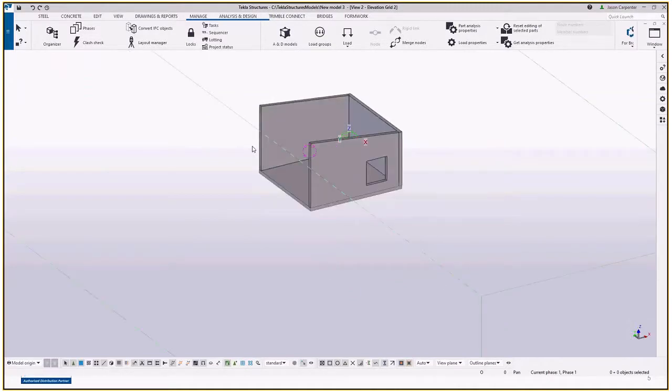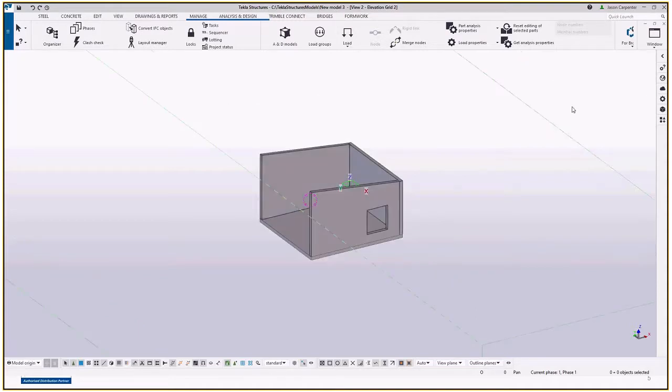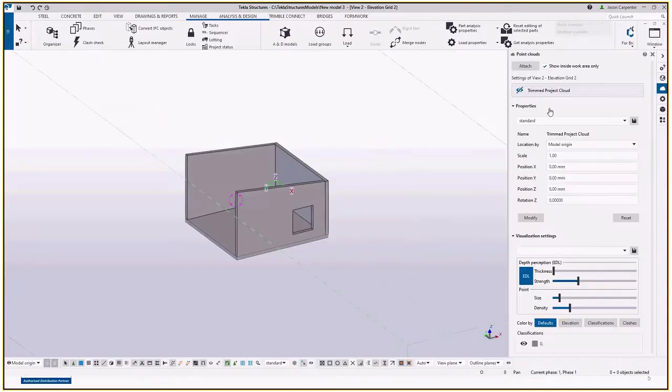With Tekla, we've got this model view here. We're able to bring in reference models, and we're also able to bring in point clouds. When you're attaching a point cloud, we're bringing these in from any other format. Basically, it's a group of points that are imported into Tekla as one unit, and each of these points may or may not have color, depending on how they've been exported from, let's say, a TX6, an X7 or a TX8, depending on what format, program and hardware you have.